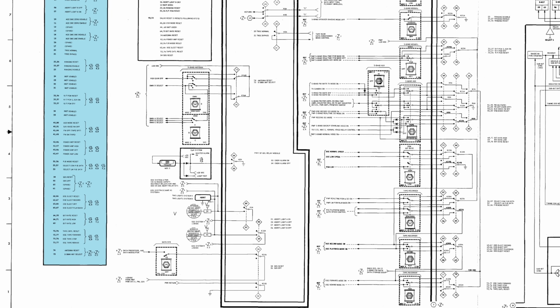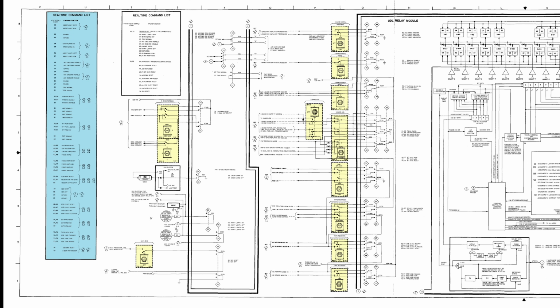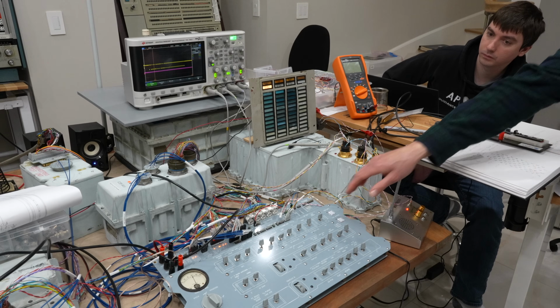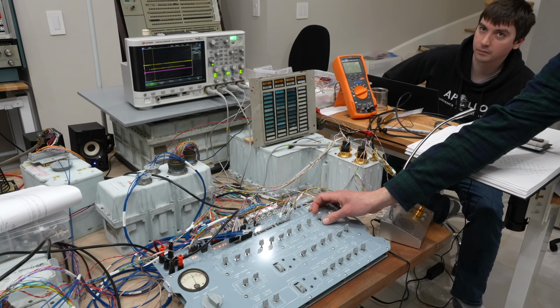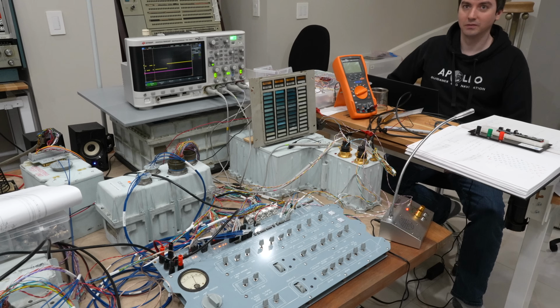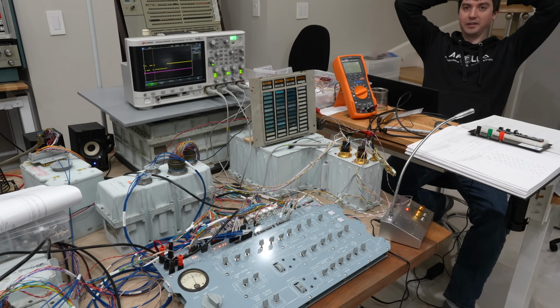These were implemented as shadow switches to the astronauts' manual switches on the control panel. The ground control relays always have precedence over the command panel switch positions, unless you flip up the magic command reset button that we just demonstrated, which would give back control to the panel by virtue of resetting the relays.